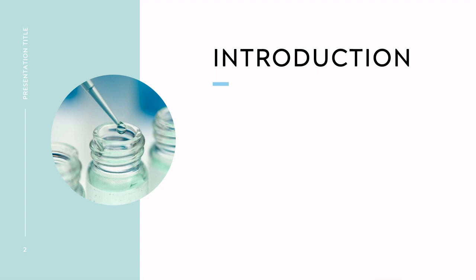So, we have discussed the basic concept of the molecular beam epitaxy process, the introduction part. The first point is that the molecular beam epitaxy process is a physical evaporation system or a physical evaporation process. That means no chemical reaction is involved in it. And there is a basic difference between molecular beam epitaxy and the other epitaxy systems. Now we compare the merits and the demerits of the molecular beam epitaxy process with respect to the vapor phase epitaxy that we have seen in our previous class.